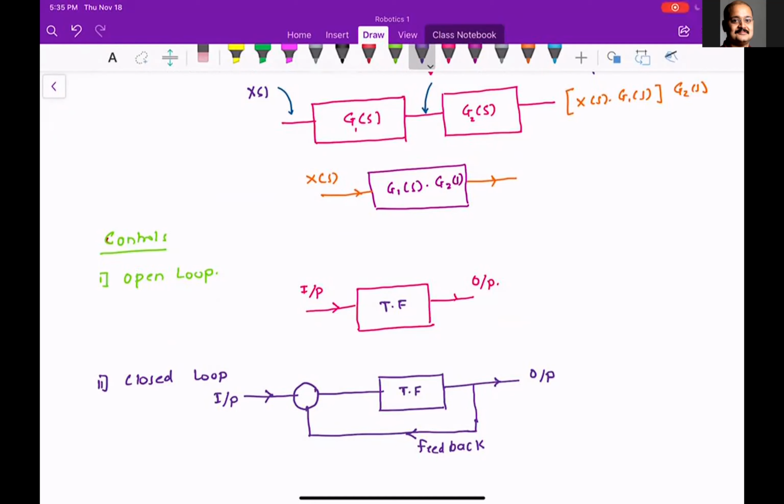But if you were to use a DC motor with some sort of feedback that I talked about in the last class, like an optical encoder, Hall effect encoder, resolver, or any other feedback, you can see what command you gave and what the response of the motor was. So if there are atmospheric disturbances, friction changes, or something else goes wrong, you can correct it inside your controller module.